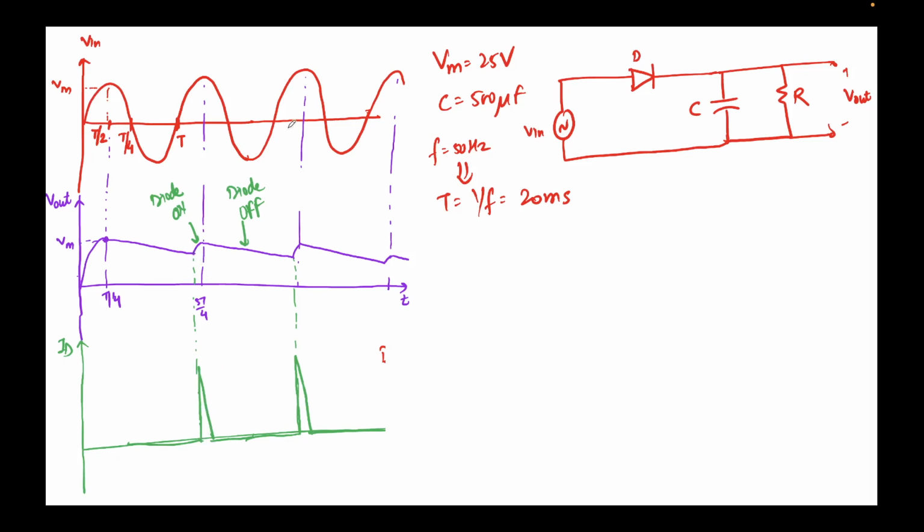Now if you remember, the diode current was an expression: Is e to the power VBE over VT. This was the expression for a diode current. I'm ignoring the -1 over here, so let's just forget about that. You can see that the higher the voltage applied across the diode, the higher will be the current, right? Or rather than VBE, this is a diode, so we can say VD.